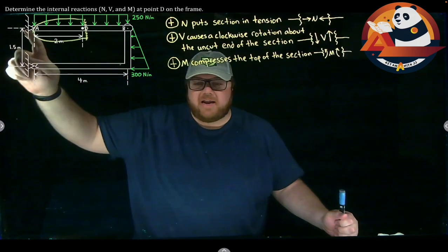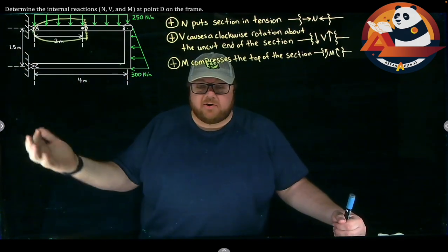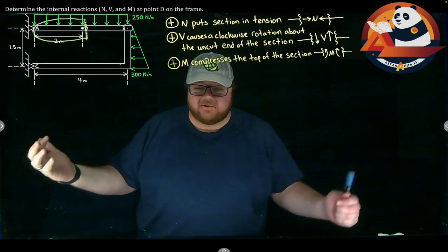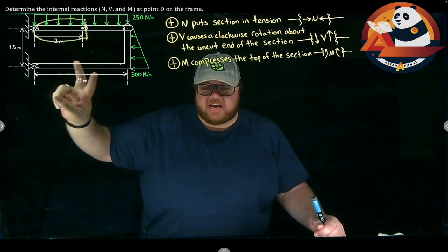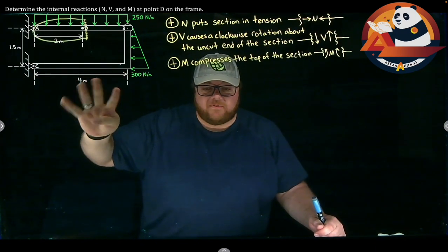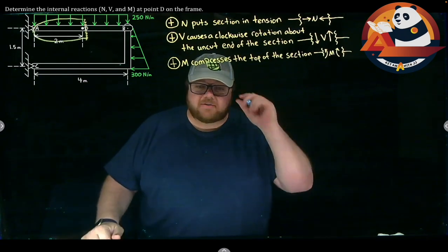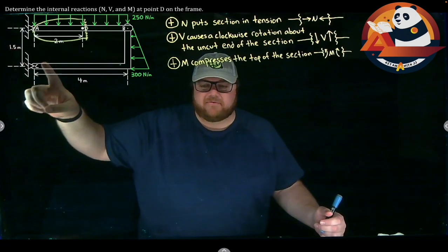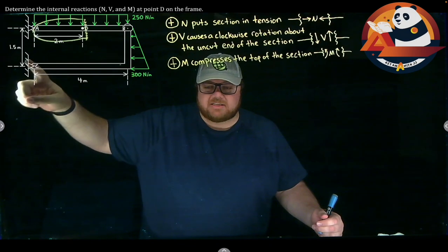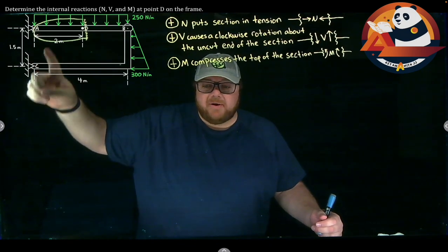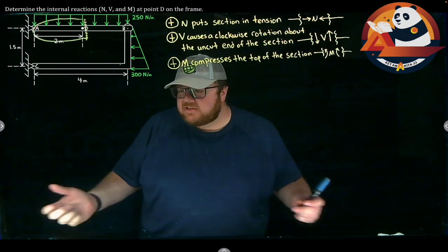So if I'm just trying to find AX and AY, could I work with an overall free body diagram and find those? Well, I would have AX, AY, CX, CY. 4 unknowns, I wouldn't be able to get all of those from that overall free body diagram of the frame. But if I drew that out and I sum moments at C, I would be able to get AX in there. So let's actually start at that point.